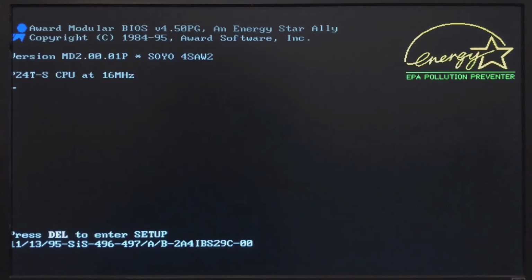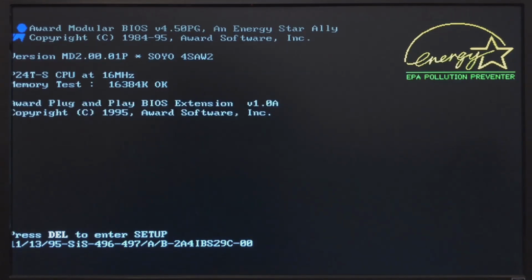And things here are very similar to what we managed to achieve with the 5x86. I got again a 2.5 MHz bus, and of course the CPU was set to 1x multiplier, so 2.5 is also the final frequency of the CPU. Now with the Pentium Overdrive the system takes too long to post, too long to just show anything on the screen. With this underclock, it basically takes 2 minutes from the time you turn on the switch until you see anything. But after that everything is more or less okay.